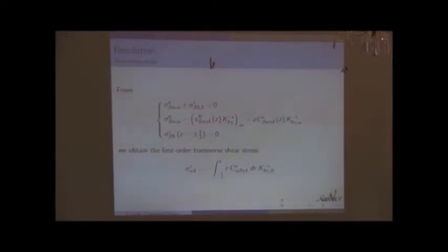If I detail this loading, I'm substituting what we just derived, the localization tensor times the curvature, and you take its divergence. It turns out that this guy does not depend on alpha because it's only a function of z. So the derivation will be carried only on the curvature tensor. It becomes a third order tensor, the gradient of the curvature, times the localization tensor.